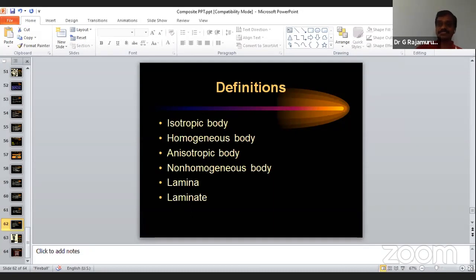I can't say this is the stirrer speed for the entire metal matrix. That depends upon the matrix, upon the particle you are going to use, and upon the volume of the particle you have added. If the volume is increased, again the agglomeration will come into the picture. You can't go to 10%, 20%, 30%; I don't want to add more reinforcement, there is no meaning in that.